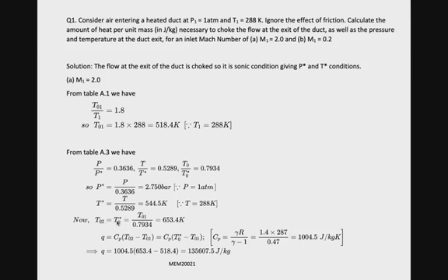Now, according to the question, we can say that stagnation temperature at point 2 is equal to stagnation temperature at the sonic condition, which is Mach number equal to 1. We can say this because the duct has only 2 points: the starting point, where we consider the initial stage of the duct, and M2 at the end part of the duct.